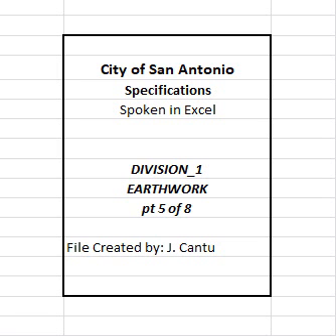Before and during rolling operations, bring each layer to the moisture content directed. Compact each layer until there is no evidence of further consolidation. Maintain a level layer to ensure uniform compaction. If the required stability or finish is lost for any reason, recompact and refinish the subgrade at no additional expense to the city.